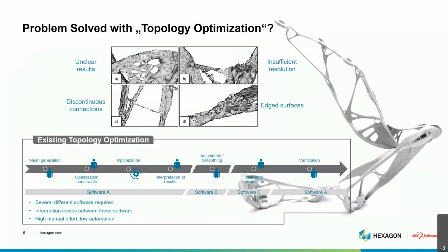And those elements that don't have big stresses or strains, or that do not have a big influence on the overall part performance, are thrown out step by step. And iteratively, a thin structure is generated.